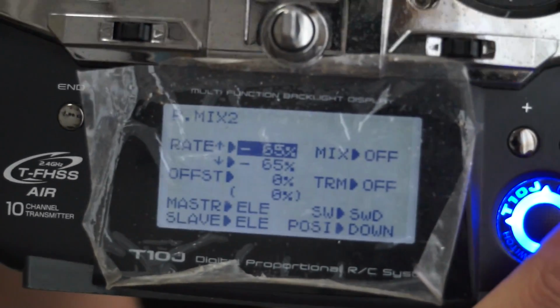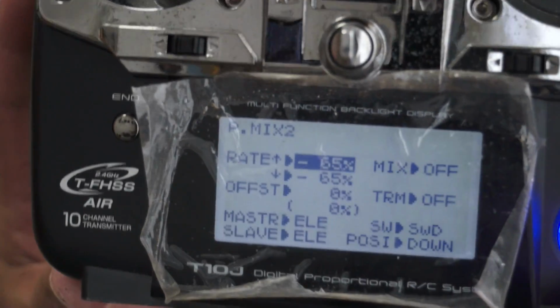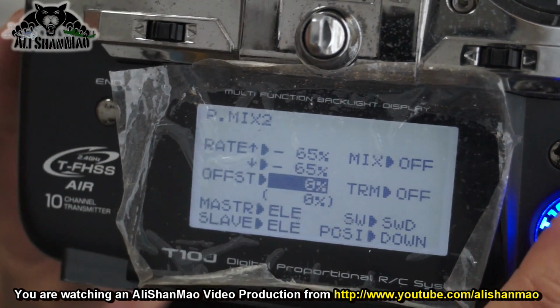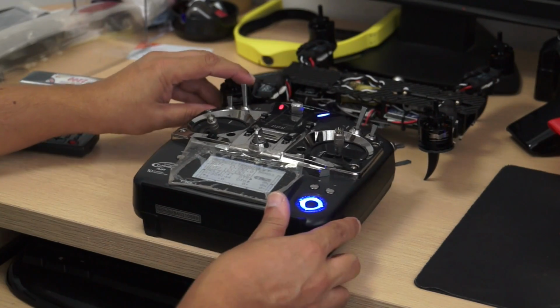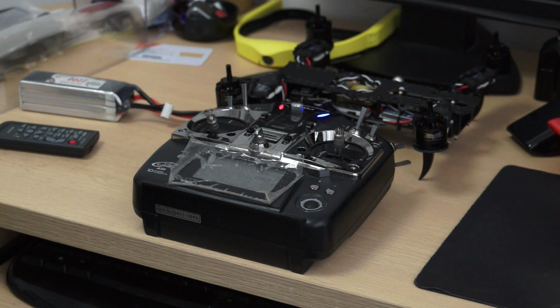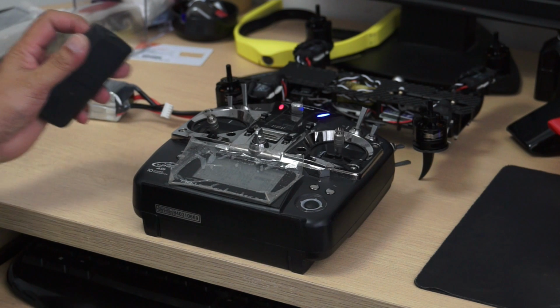Generally, I found, according to my experience, 50% to 65% are the best range for these values, elevator to elevator mixing values. So go with minus 50% to minus 65% at the max. Okay? So I hope this all is clear about the radio programming and how you will use your mixing in order to control the rotor tilting. Now the next step is to program the CC3D. Let us do that right away, and it's also a very simple piece of cake.